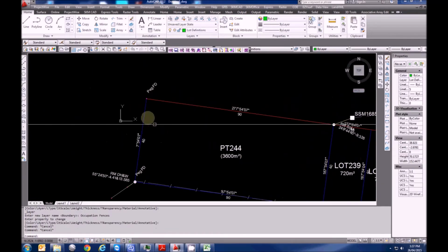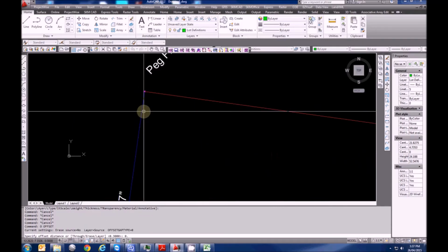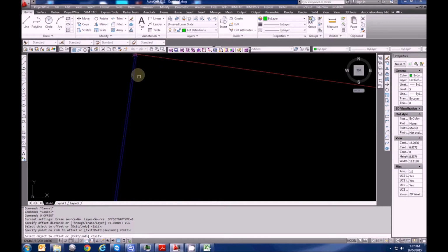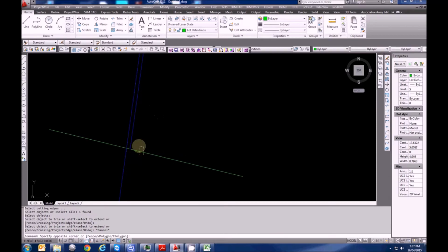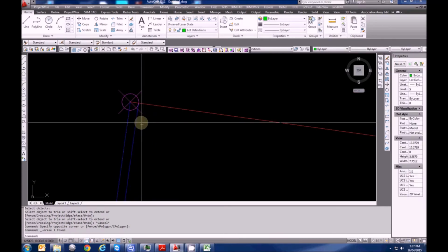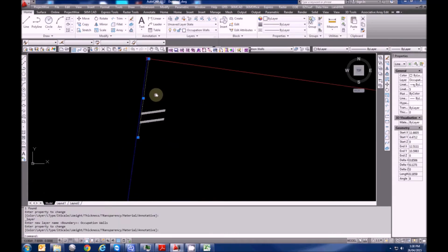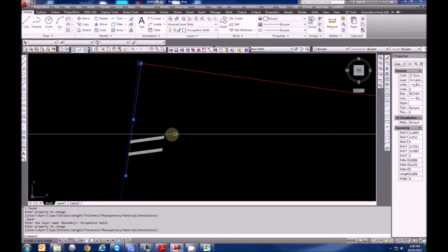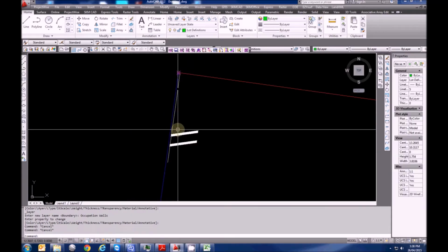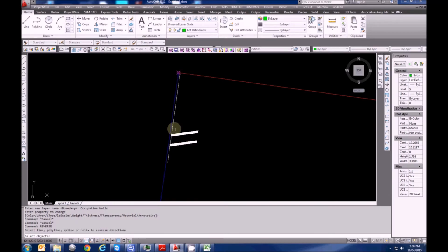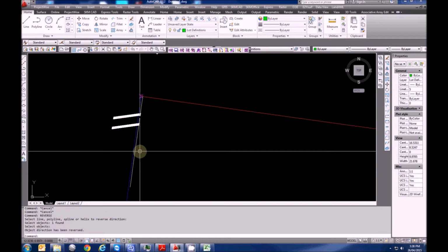And we'll actually add a building wall. So there's a building on this side which is over 0.1. It doesn't run all the way along, we'll just pop it off, so about there. It is actually on the front boundary at the front here, so we'll put that in as wall, occupation walls. So you can see there it's actually put the wall in the wrong direction, saying that the building's on this side, which is not actually correct. So we're going to use the reverse tool, which is a standard AutoCAD command. Pick that up, and that'll reverse our line round the other way.